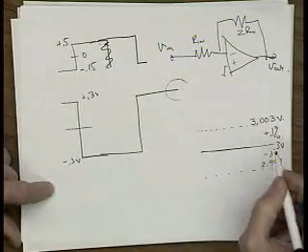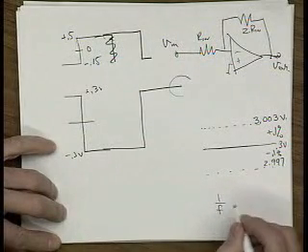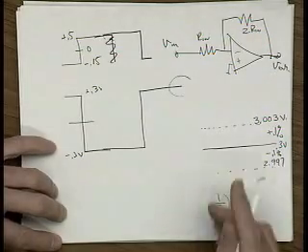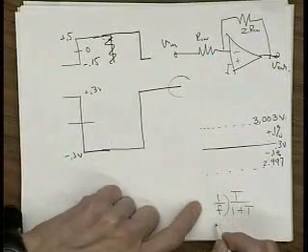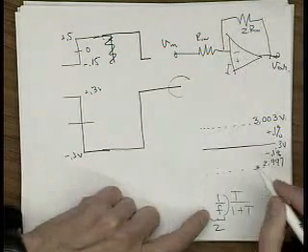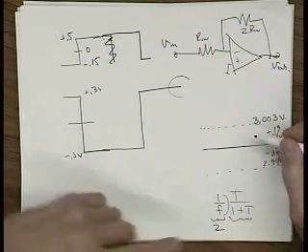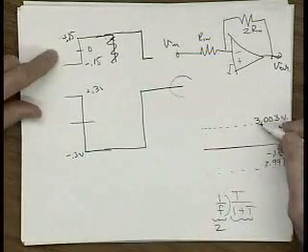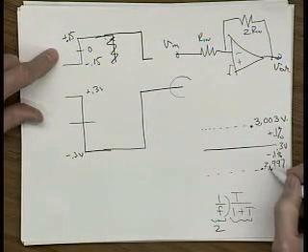The response of this amplifier should be 1 over f times T over 1 plus T. Modulo the Rn and so on, this thing should have a gain of exactly 2, because we'll assume these resistors are exactly a factor of 2 apart, times this other term. So if we have 0.15 volts in, we'd like to have plus or minus 0.3 volts out. This is 0.2997, I guess, not 3 volts.